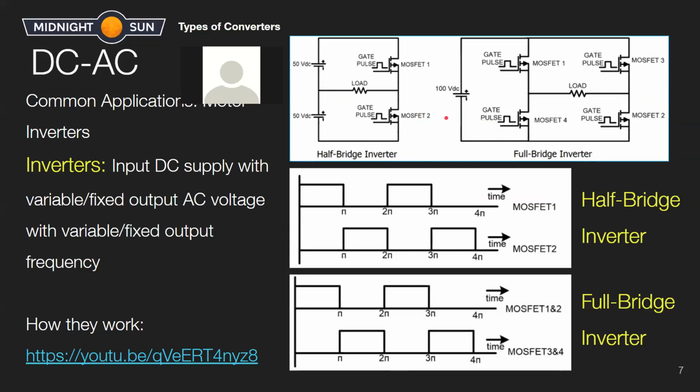This is like a sneak peek to the video, but if you look at the comparator, which usually takes in a triangular waveform and a sine waveform as inputs, those two compared will give you the width to which you PWM your FETs, and you will soon resemble a sinusoidal waveform through the pulsation of your PWM. So I probably explained that way worse than I needed to, but definitely check out the YouTube video. It's very clear.